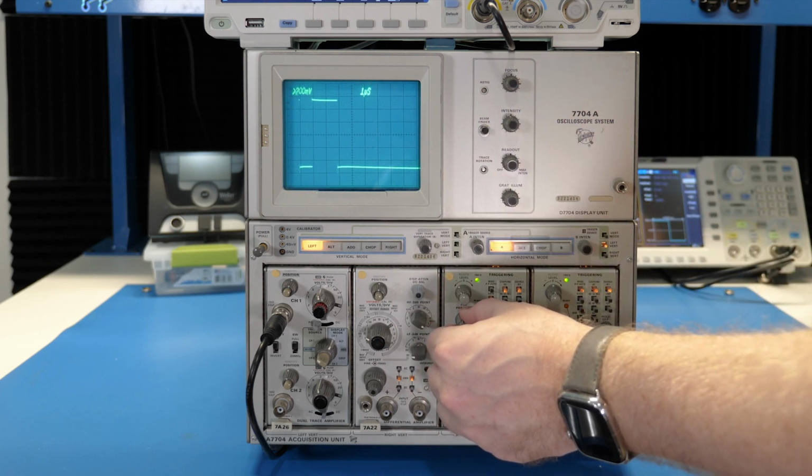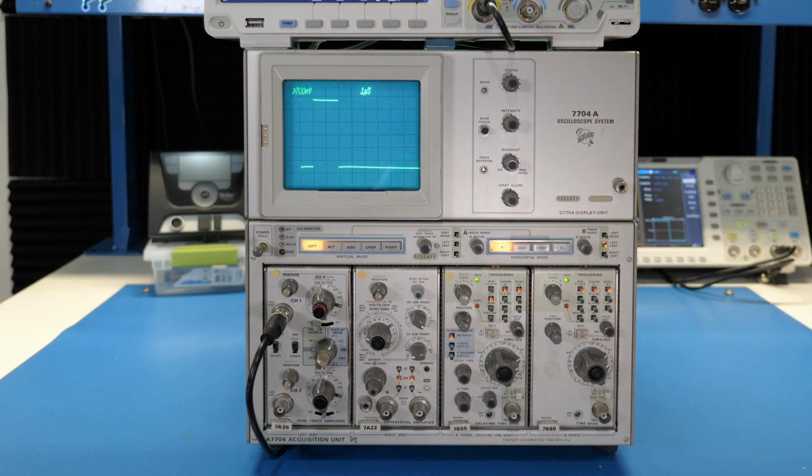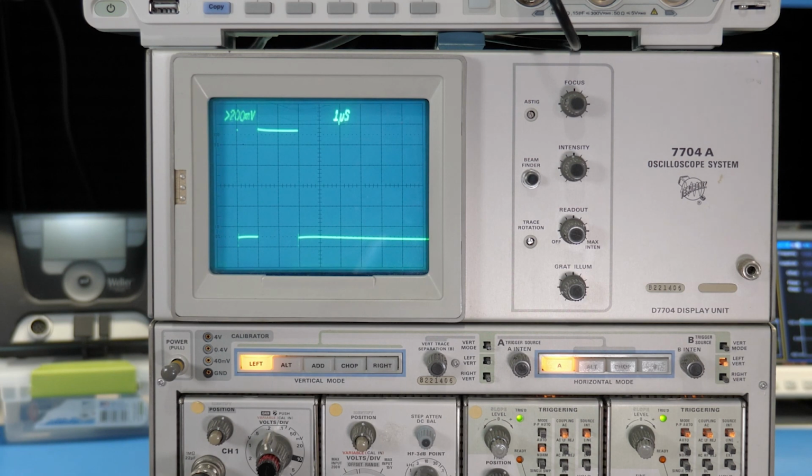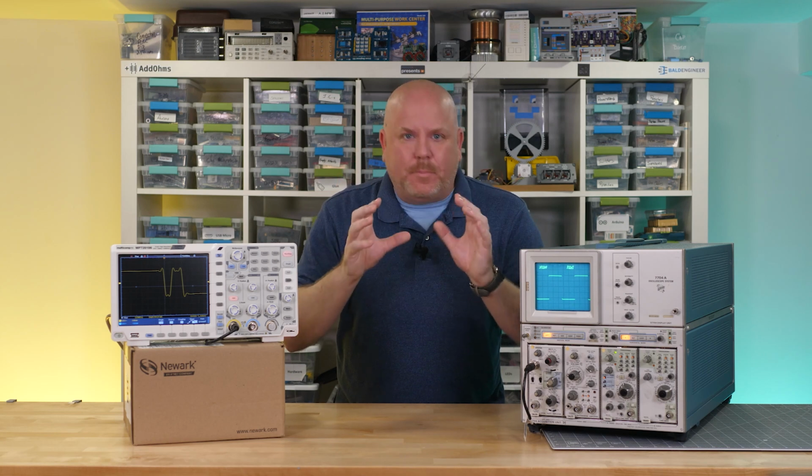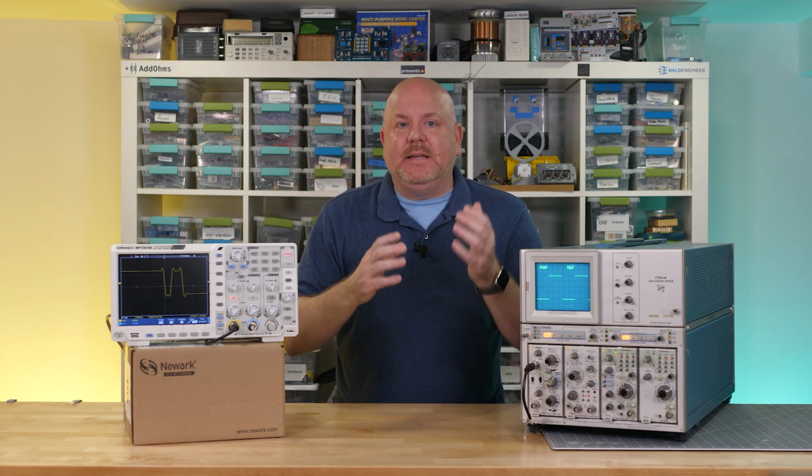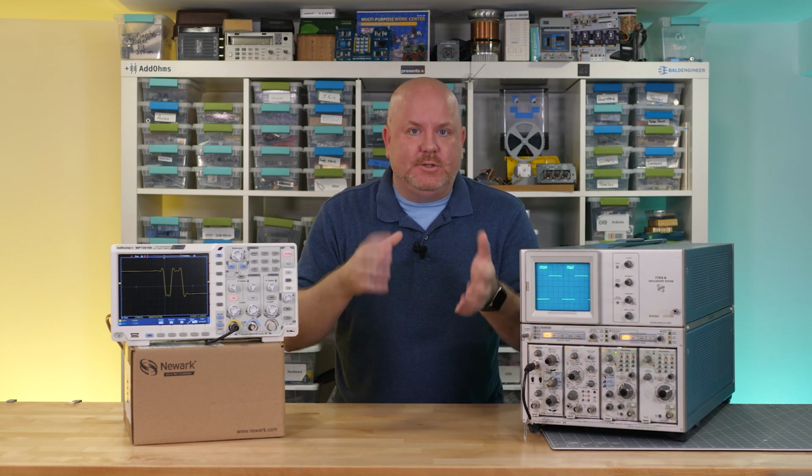If you've never looked at an analog scope before, you may not realize we've already seen this exact waveform. Look close at the screen's left side. Since we triggered on the falling edge, and the trigger starts the analog scope sweep, we just barely see the edge before the glitch. But that's not the point of this video. That's basically the same thing we did on the digital scope when we stopped it and zoomed in.